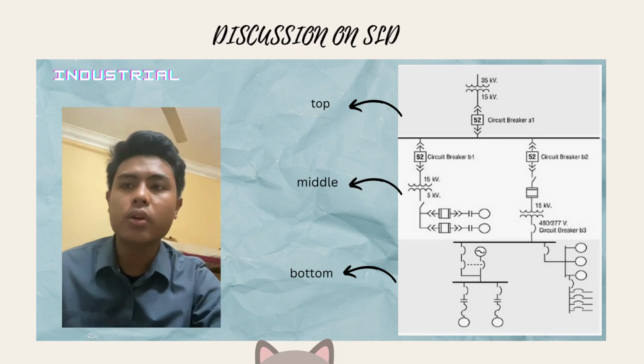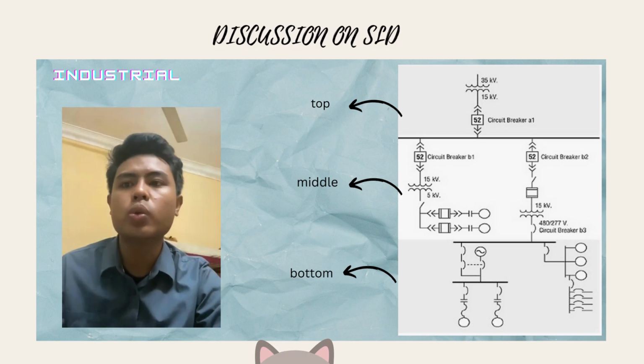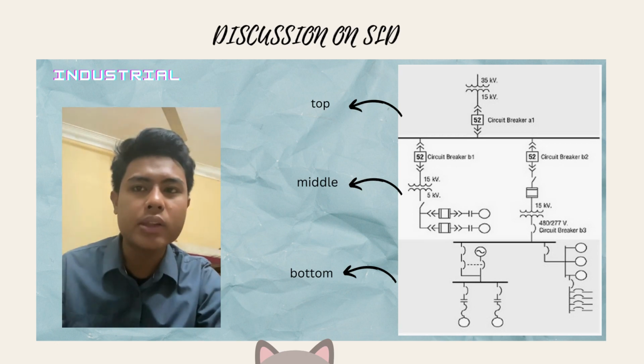The second drawout circuit breaker is coupled to a step down transformer and a fuse disconnect switch. Due to the voltage being stepped down again to 600 volts or less, all equipment below the transformer is now regarded as low voltage equipment.